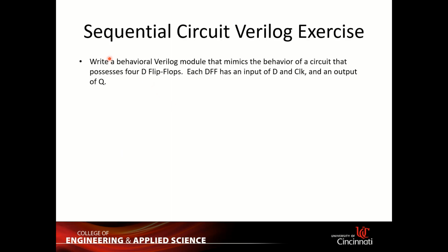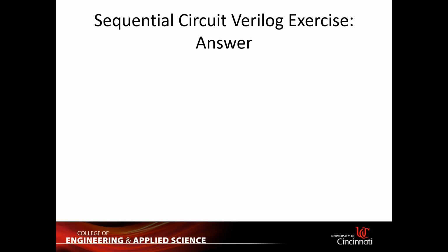So let's go through an exercise with a sequential circuit in Verilog. Let's try to write a behavioral Verilog module that mimics the behavior of a circuit that possesses 4 D flip-flops. Each D flip-flop has an input of D and clock and an output of Q. Assume each D flip-flop triggers on the positive edge. So let's go through this exercise together.